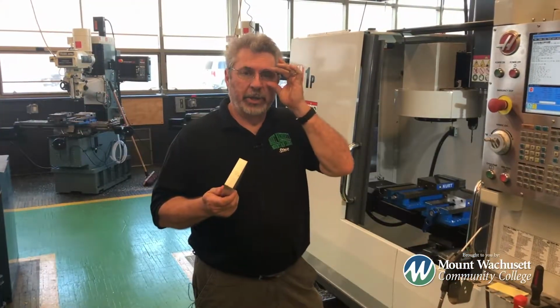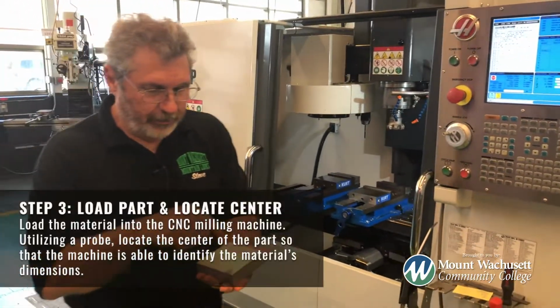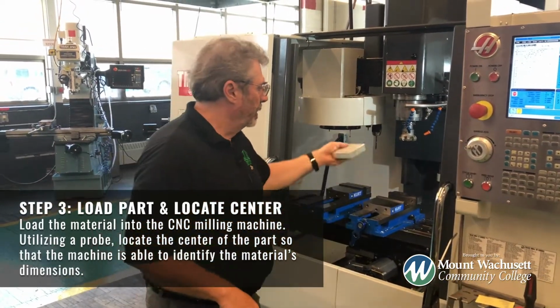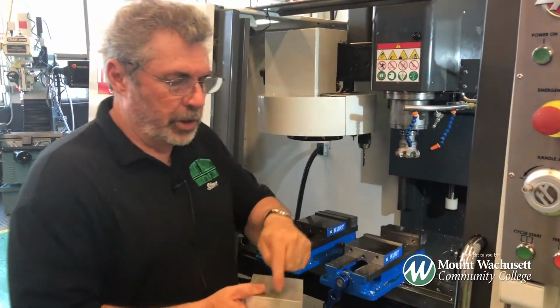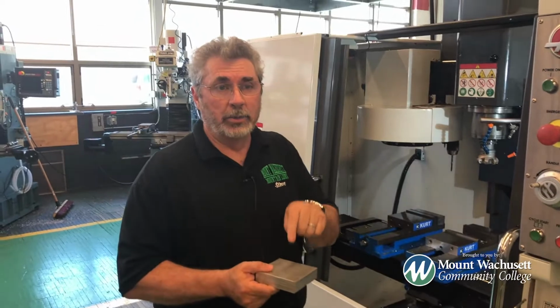Now we're over at our CNC milling machine. We're going to load the part in the machine, and we have to find the center of the part in order to start machining it, because the machine does not know where this part is while it's in the machine. We have to pick it up with what we call a probe. There's a probe in here that will indicate the outside and find the center of our part, and that's what we're calling 0 today.